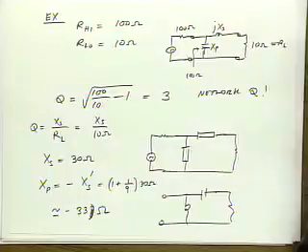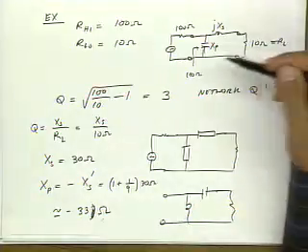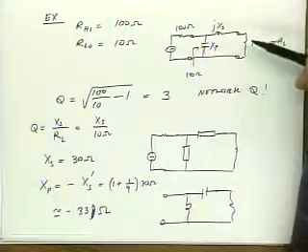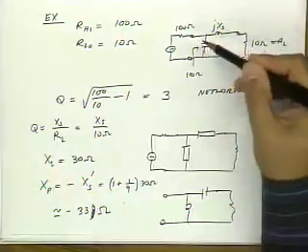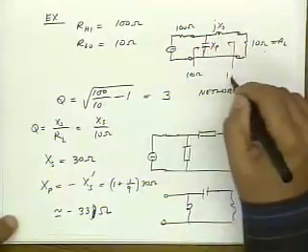Okay, well, this is a nice way of taking a low impedance and making it high impedance. What about the reverse process? How do I make a high impedance a low impedance? Any guesses? Yeah, the other way around, right? In fact, this is a symmetric network. It transforms 10 ohms to 100 ohms, but if I look here, it also transforms 100 ohms into 10 ohms.